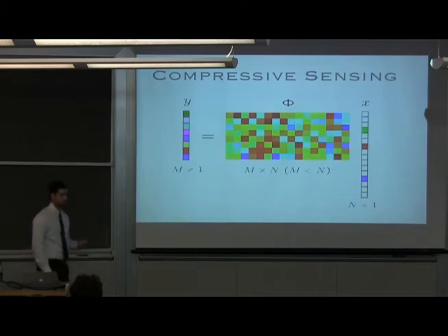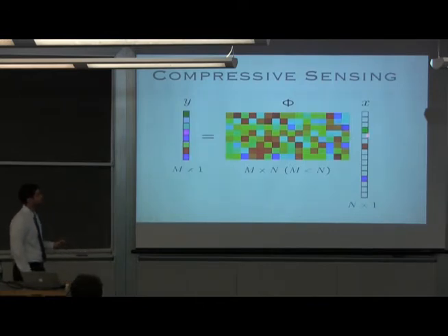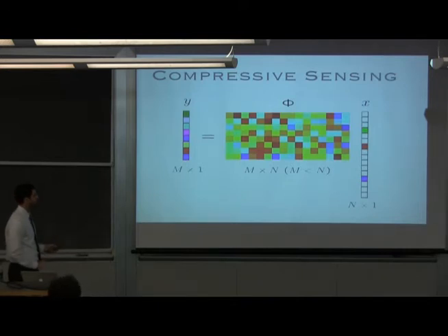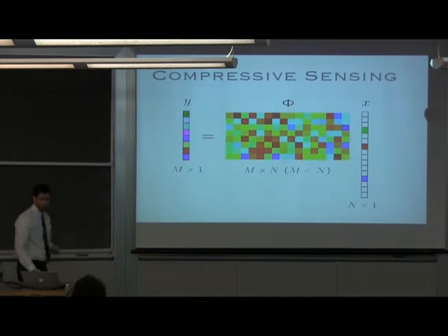So the idea behind compressive sensing is you have some sparse vector. This could, for example, be a wavelet representation of our image. Most of the coefficients are 0, and some of them are non-zeros. The non-zeros here represent the largest weighted wavelet coefficients. You acquire measurements by multiplying the image by some matrix phi. So in our case, this would be like our +1, -1 matrices that we use on a single pixel camera. And you acquire a small number of measurements y. And it turns out that, provided that this vector you're trying to measure is sparse, you can actually reconstruct it exactly using a very small number of measurements, provided that this sensing matrix phi is constructed properly.